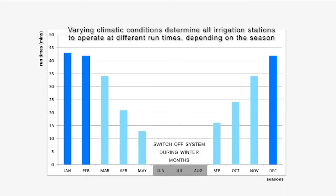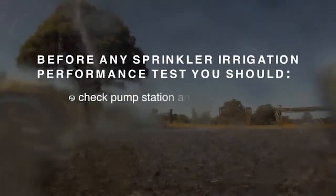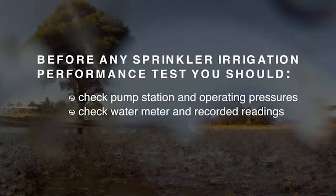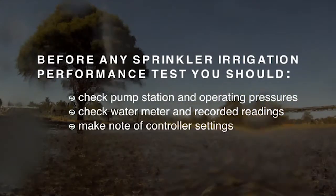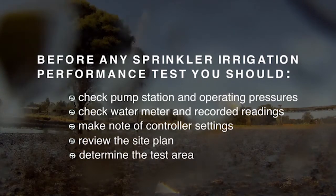So, to summarise, you have now checked the pump station and operating pressures, you have checked the water meter and recorded readings, you have noted the controller settings, and you have reviewed the site plan and determined the test area.